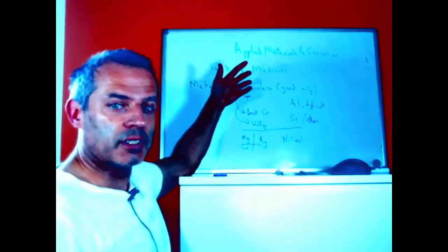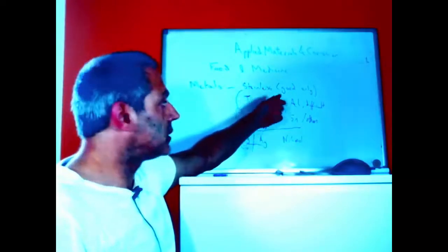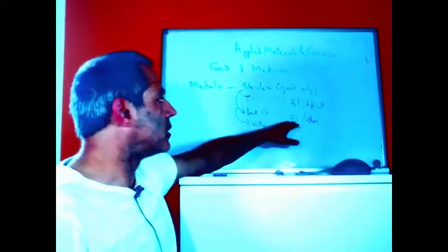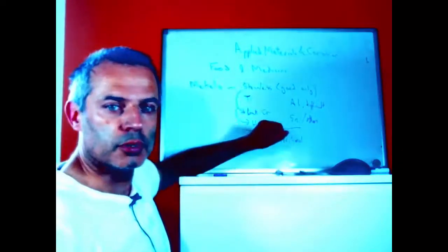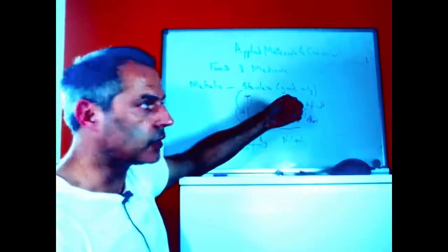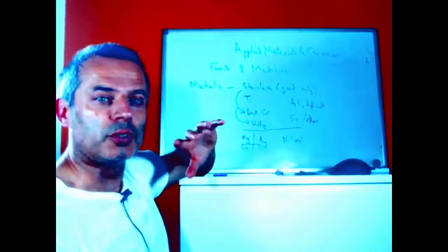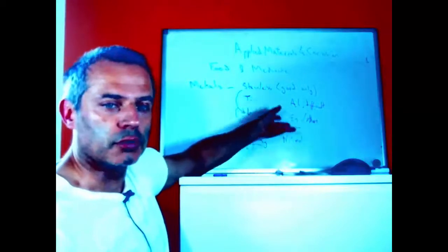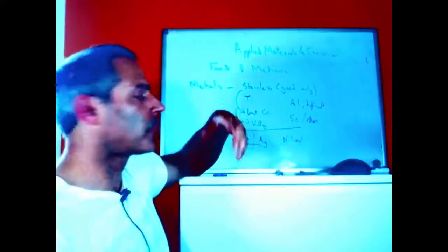However, on the other hand, some materials used in the past, like tin for tin cans, or some materials used still, avoid this problem a little bit. So those are heat treated, steam treated in the absence of oxygen. They don't oxidize too badly, and then they are anaerobic for the rest of their lifetime. A tin can is a big problem to users if they don't know how to use them, because if you open it and leave the material in there, the metal starts to dissolve into the food quite quickly as soon as it is exposed to oxygen, because then we can have a corrosion cell.